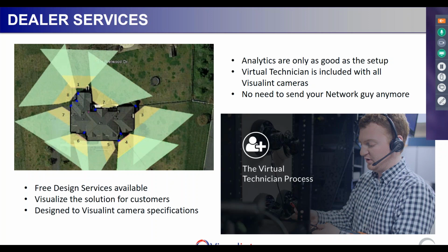There's not a true standard in the US yet for video surveillance and pixels per foot, so we use the British standard when we're doing our system design, so we know that what we're showing you on the plan is pretty accurate for what you will get when you get on site. It's part of the system design pack. You get the resolution breakdown, so the pixels per foot, what's recognition, what's identification, for example.